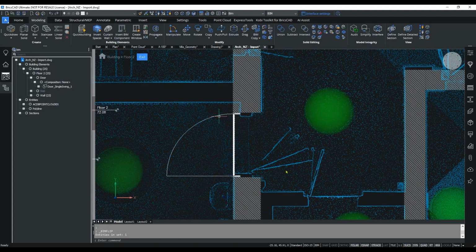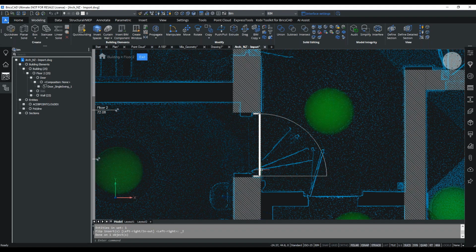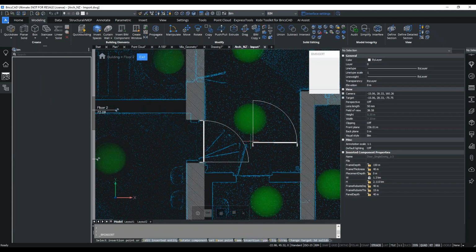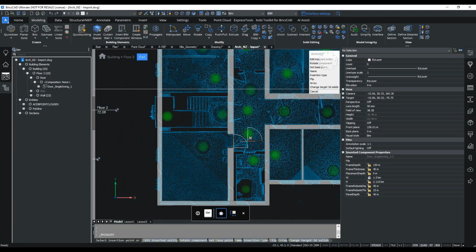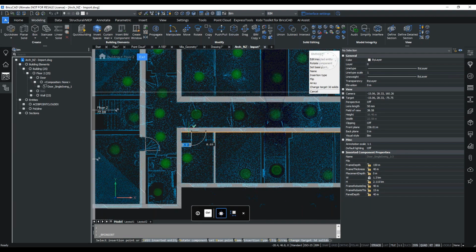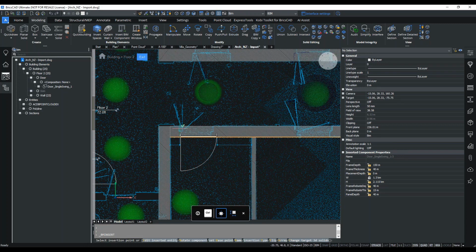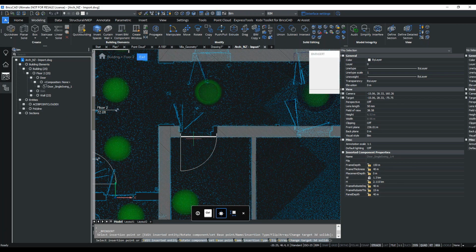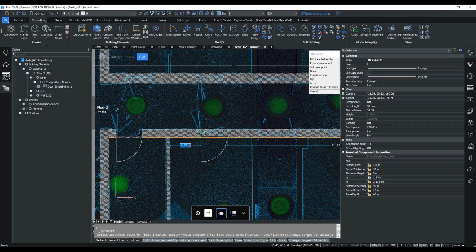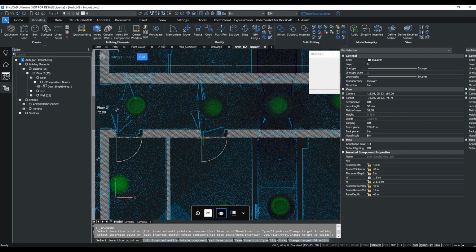And what you normally do is get it correct once, and if that door is then repeated throughout the building, which is an ideal scenario, you can hover over it and click on the insert command, and we'll take those parameters and let you copy it around the file. So I'll assume that these are the same, though they're actually slightly different, but for the sake of speed, let's put these in.